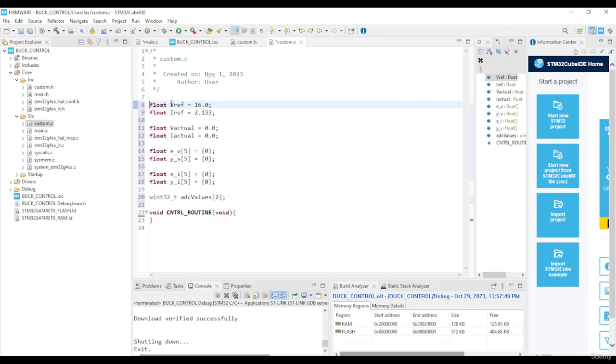So defining them in the main file and just including an extern in front of them in any additional C file helps a lot for me to follow. Keep in mind that this is C code. It could be implemented in a lot of ways. I'm essentially just showing one way that has worked for me in all my implementations of closed loop control.